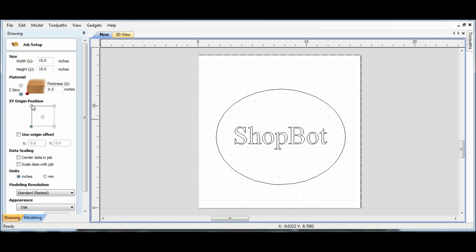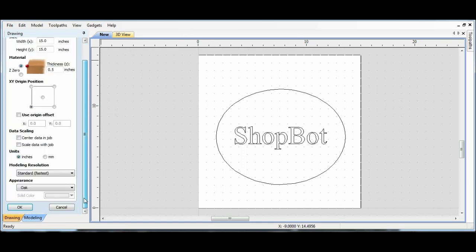Only thing better I mean by that is you're going to save your spoil board a little bit. Cutting on the top is definitely safer, but you do have to be a little more careful dialing in the thickness of your material. So leave the zero to the top until you know better. And that's exactly how I'm going to teach you, and that's exactly how I use it. So don't think it's just a bad way to do it.